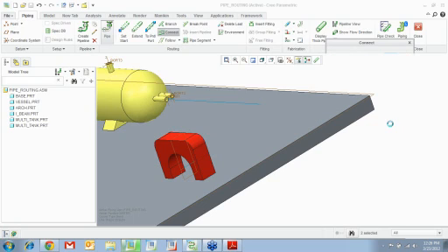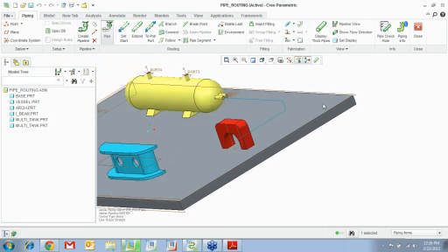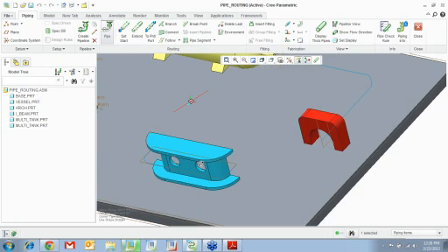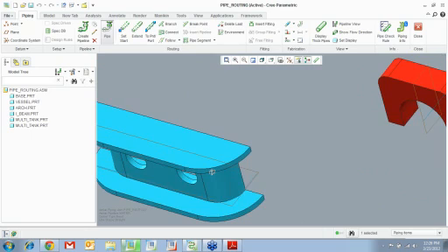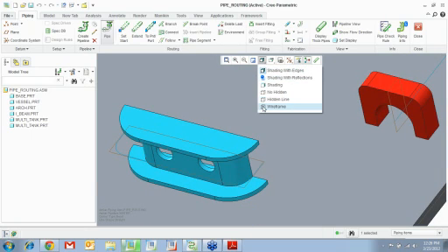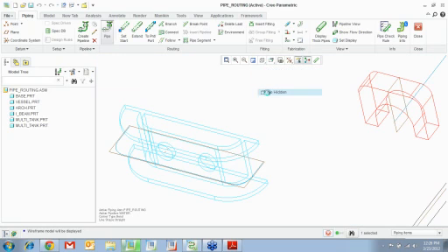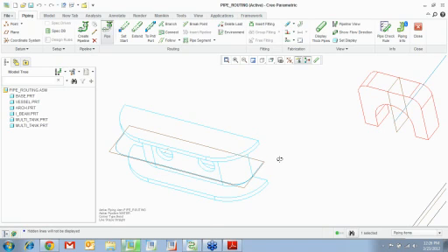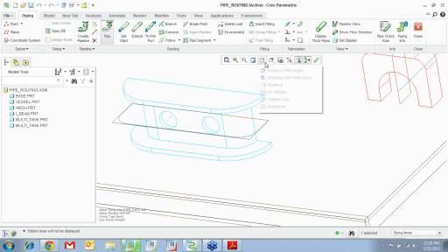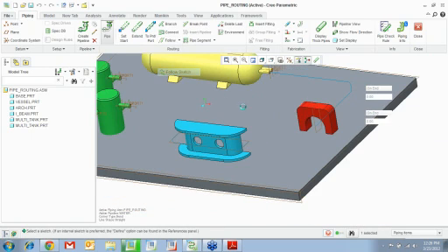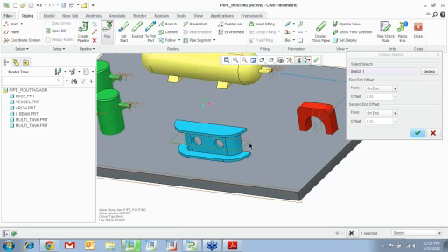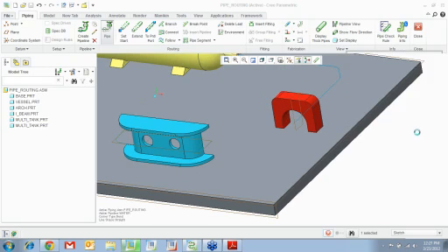Alright. So now that you've connected that, I want you to also see that there is a little sketch over here. Fortunately, that part's in blue color. It's very bad of me to do that, but you can see there is a sketch on that particular plane that I'm going to use to follow. So I can say follow a sketch. I'm going to pick that sketch. I'm going to go from the start of the sketch to the end of the sketch and say OK.